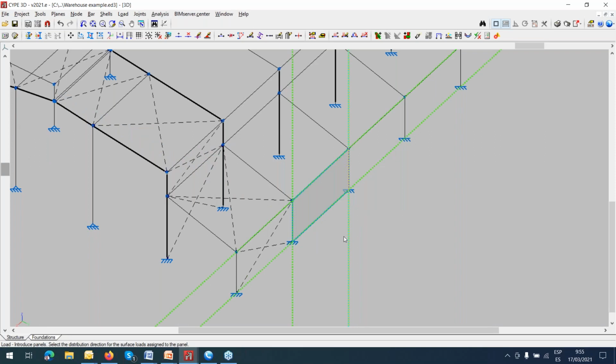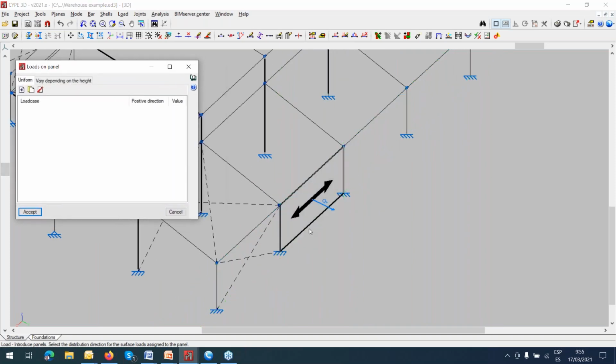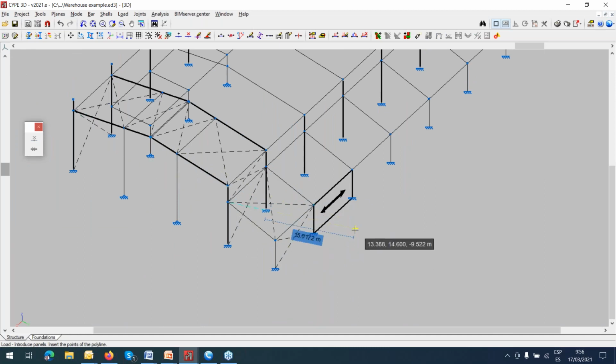And now the best way to introduce this is, suppose that the wind is coming from the right to left or in any direction. It's better to show that these winds are going to displace differently. The way I'm going to study the effect of that wind on the structure is up to me. So suppose I choose this direction, and now you see any effect of this wind will be distributed in these two bars. Okay, then I can start using different kinds of options here. If it's a new one, I can introduce a new one, not only the one that we have as a reference, and give any value here. After that, if you run the analysis, you will see that displacements and the solicitations in that area are going to change drastically.